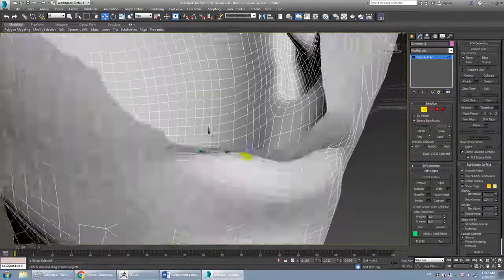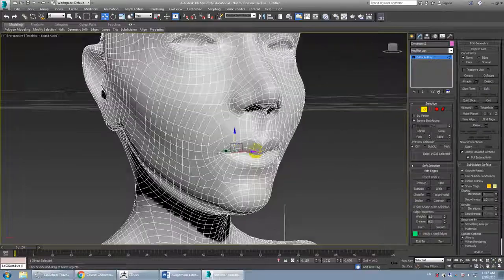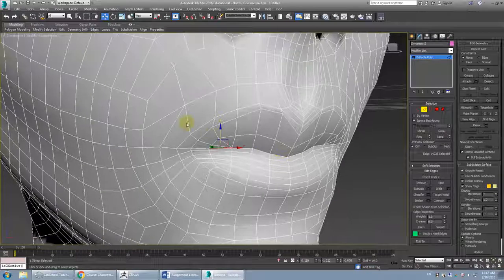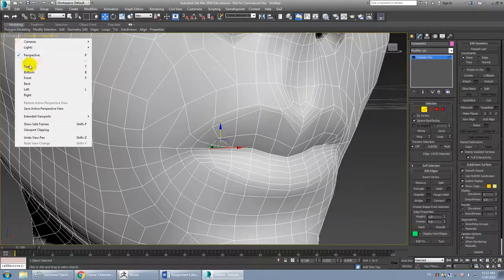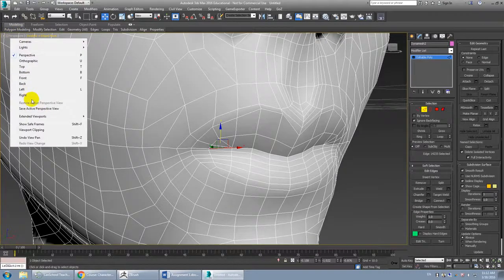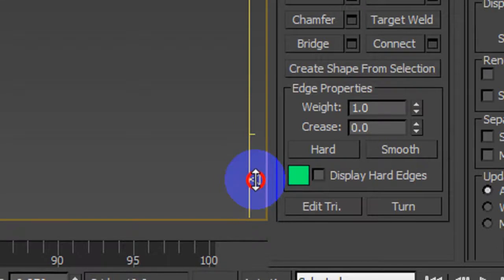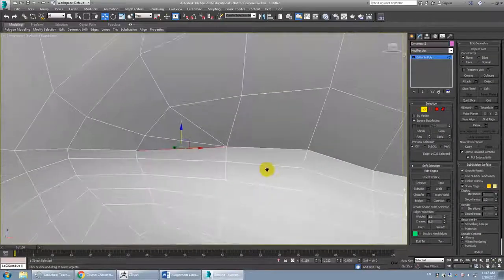One thing you may also encounter, this may happen in Max or Maya, you see when you have objects that are very small, like ZBrush's working scale is actually quite tiny, and so it's very difficult to zoom in. You'll want to look for this in Maya if you're working in Maya as well. It's got the same kind of label, set up a little bit differently, of course, but if in Max you go to perspective and viewport clipping, this is basically the range at which the camera cuts off the visibility of an object. And the lower, it sort of puts this yellow bar on the side. And if I drop this lower notch down, I should be able to zoom in much, much closer to the object without it kind of cutting off the mesh.